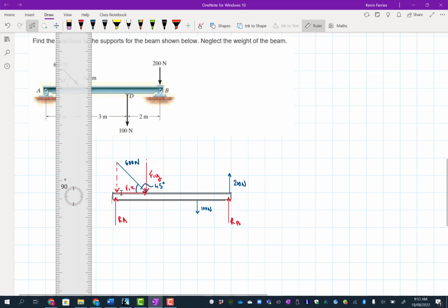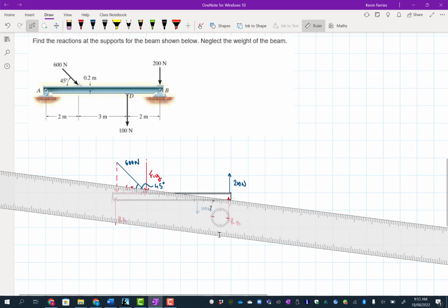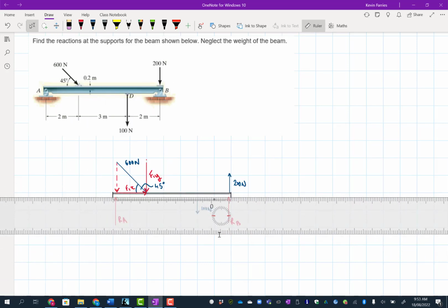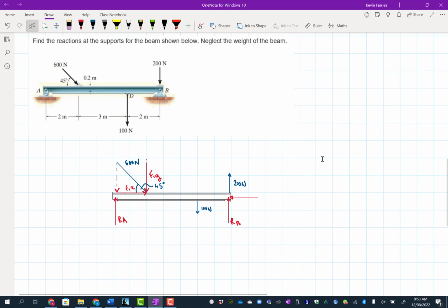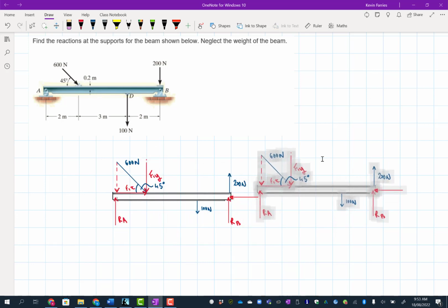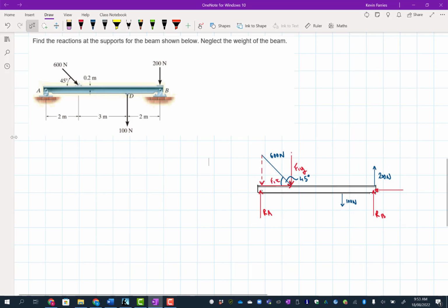Okay, so we've got one F1X, so we've got one component of X in this direction. The reaction to that, the thing that's making this beam stable and not slide to the right, is the fact that there must be a balancing reaction at this side. So when we're checking overall stability, we're checking sliding in both the x direction and y direction, and we're also checking total moment. That's where you get sum Fx equals 0, sum Fy equals 0, and sum of the moments equals 0 for rigid body equilibrium, where all the forces don't cross at one point. If they did cross at one point, you'd lose all your moments because there's no lever arm. Therefore, you just need sum of the Fx components equals 0 and sum of the Fy components equals 0.